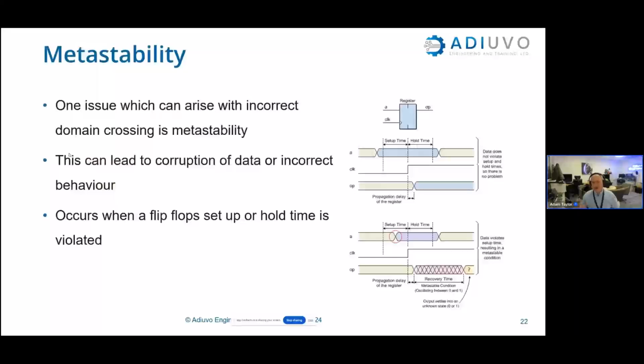or you can run the clock interaction report as well, which will give you a good indication of what's going on in your design, and how the clocks are interacting with each other, whether they're timed safely, whether they're untimed, whether they're unsafely timed, whether there's no timing relationship between the two.